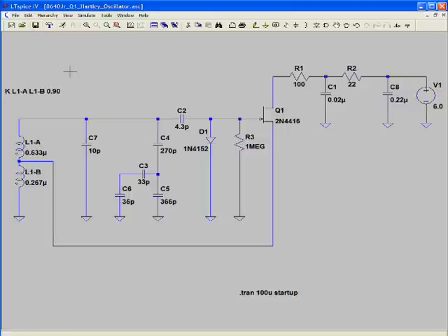and save it. So what did we learn? Well, we learned that we can use a tapped inductor by creating two inductors in SPICE and connecting them together, and putting a SPICE directive up here that creates a mutual inductance between the two, which makes them so that they act more like a real inductor. We learned how to insert new components into the library, how to do the FFT analysis, spectrum analysis, and how to change component values on the fly and see what happens.